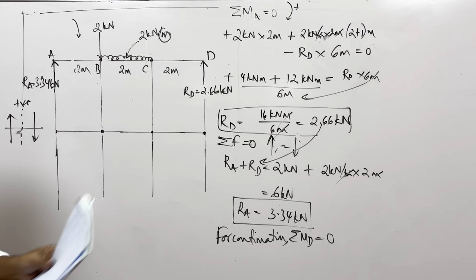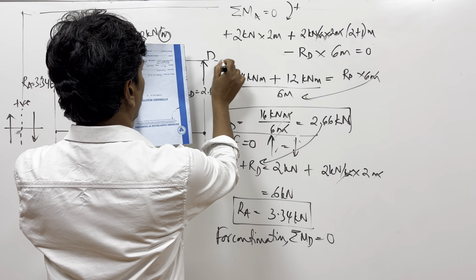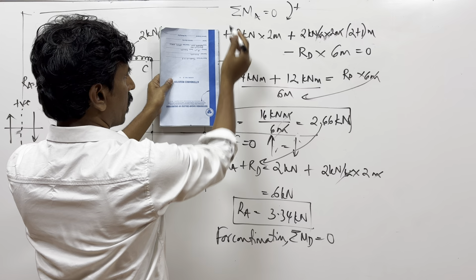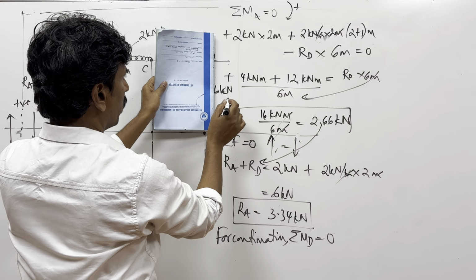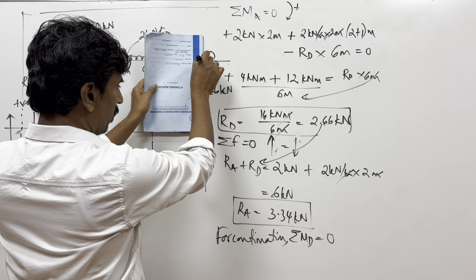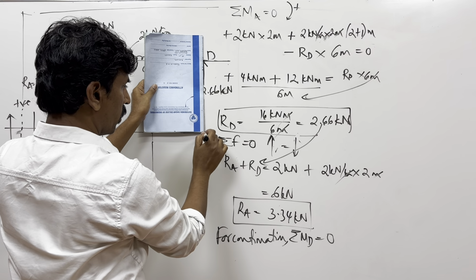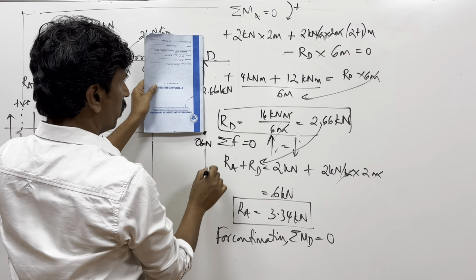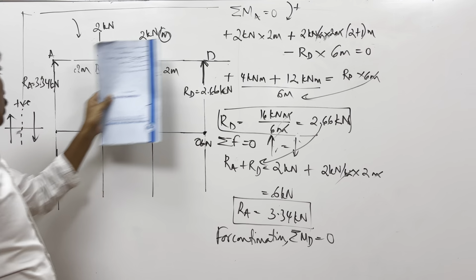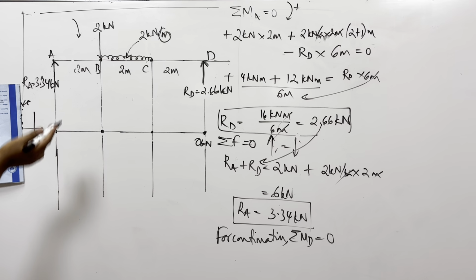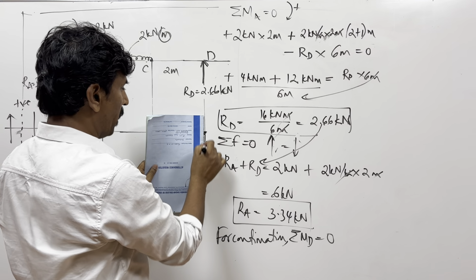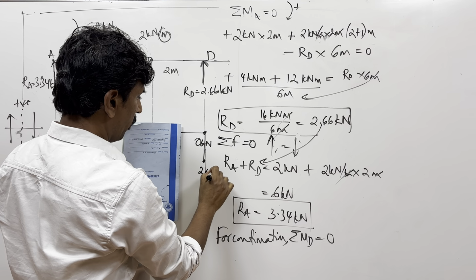So as per this, if you imagine that the beam continues here, and there are no forces downwards or upwards, it is 0, 0, 0 until it reaches this point. Until it reaches this point also it is 0 because there are no forces here. So I write it as 0 kilonewton. Then as I go further here, I see one force going upwards on the right hand side. Is it positive or negative? It's negative. So it goes from 0 to minus 2.66.